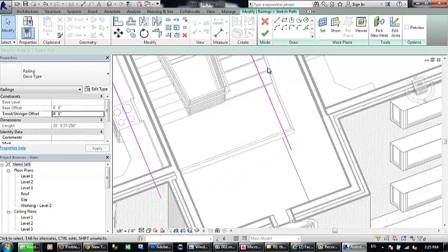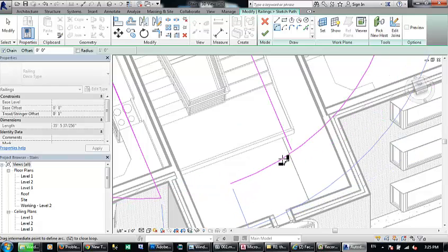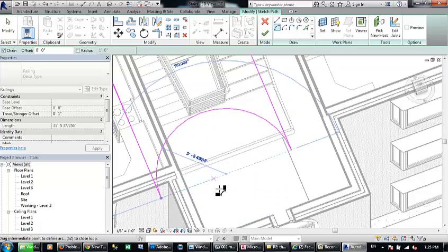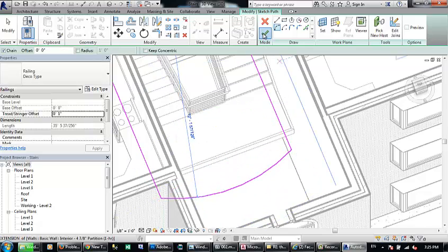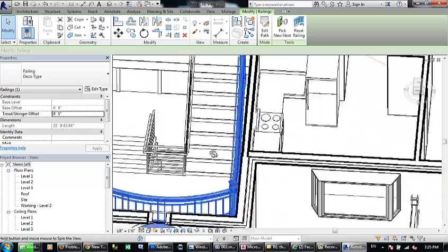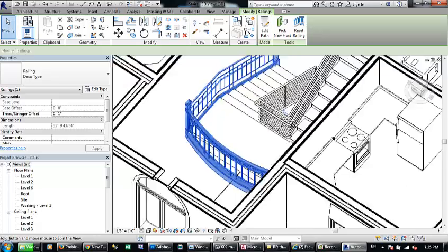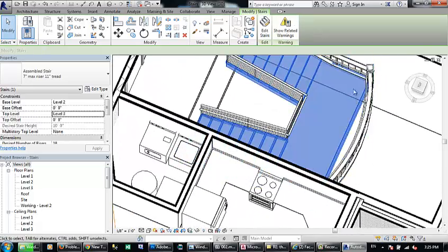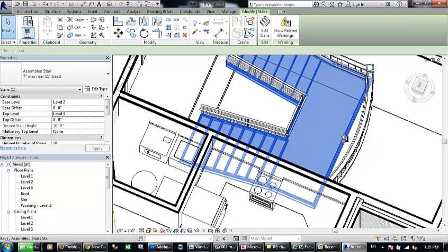So if you delete this one and create a curve with 3 points, you have to click the first one, the last one, click finish. So here's how it will look. But you have also to tweak this one accordingly, so it's running as a curve.